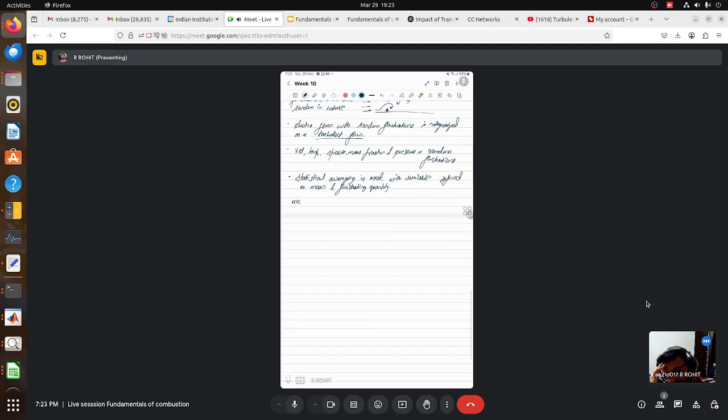So one important thing is the mean values are calculated for a time average over a sufficiently long time period. So you need to wait a sufficiently long time before you calculate the mean values, so that the mean value does not change. Mean values will not change if you increase your time more.